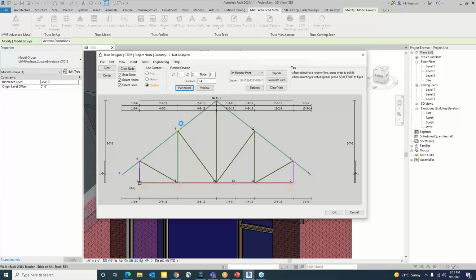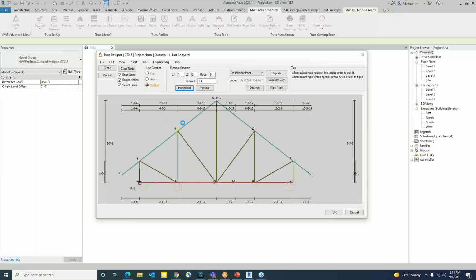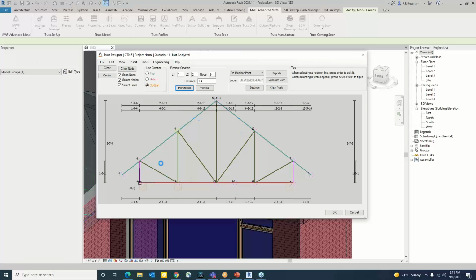When it starts running, it will select each member of the truss and check the family for that member. If it fails with that family, it will go ahead and select the next one on the list and check it for that member. So right now, it will start checking it for top tracks, bottom tracks, heels, and webbings. And when it is done, it has passed now.